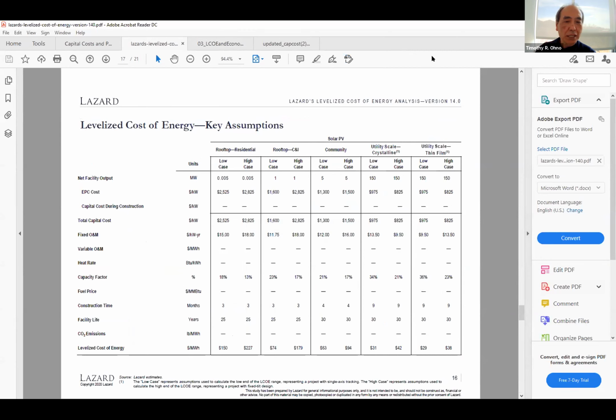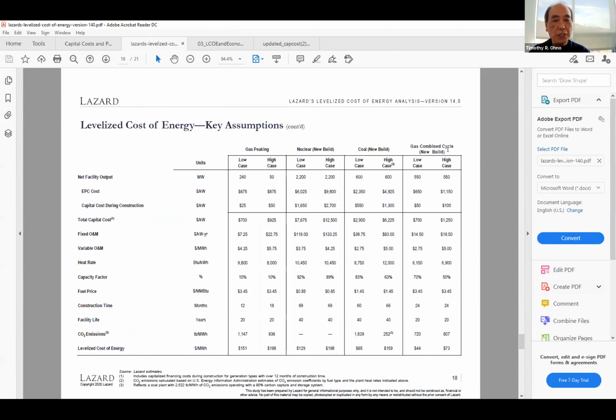So in the key assumptions, let's find my coal again. So here's my coal. If I assume that I'm building a new plant, and I've done really, really well, the low case is I really optimize my plant so that I get the lowest cost possible for the LCOE. What are the things that are included in that? I could see one way I could do that is I keep the plant running all the time. So their argument is that best case scenario is I've designed a plant that runs well, so it runs 83% of the time. And that's very much like the 85 number we've seen already. It's also got the other things in theory in here, but I wanted to use the EIA data rather than try and focus on this one.